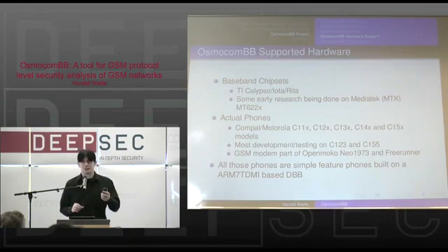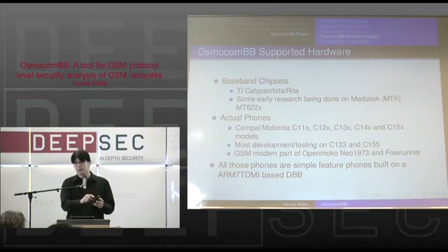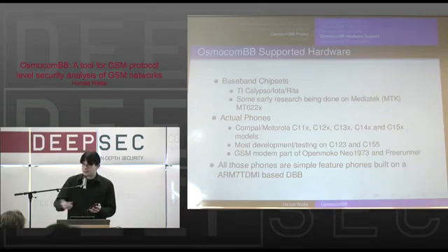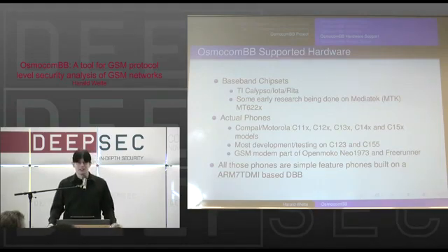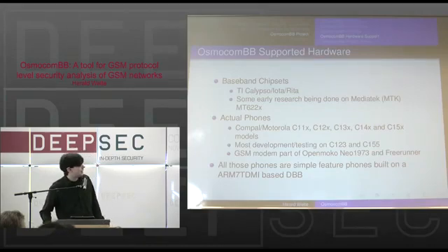Interestingly, downloading software on those devices is extremely easy. You just press the power button, and after you press the power button, it tries to negotiate with some host software. And if there is some host software, the bootloader that already is in the phone as it ships from the manufacturer will download the executable code over the serial line, and it will jump to it. It couldn't be any easier. There's no protection whatsoever. There's no digital rights management, no cryptographic signatures, nothing. You push the power button and it will happily download any code that you send it.